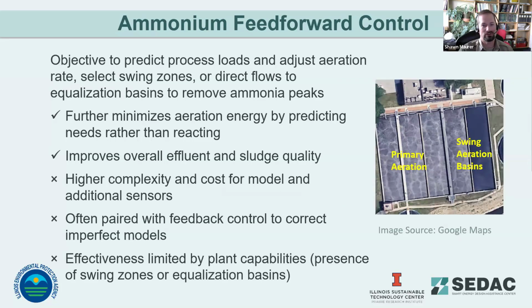And then there's feed forward controls where you're actually feeding your ammonium readings into a model of the plant and predicting how the plant's going to react, and then adjusting your set points and amount of aeration available in your plant to meet those treatment targets. So the main limiting factor in addressing ammonium peaks is the existing mass of nitrifiers in the process. And since that factor changes slowly, just adjusting the DO set point or solids retention time through trying to do more recycle in the basin isn't going to have as fast a reaction as you need.